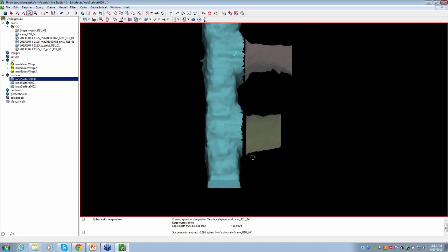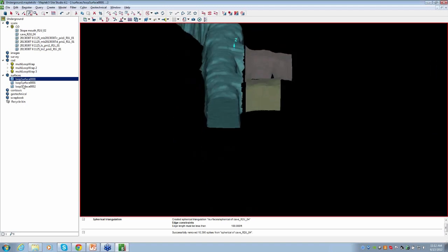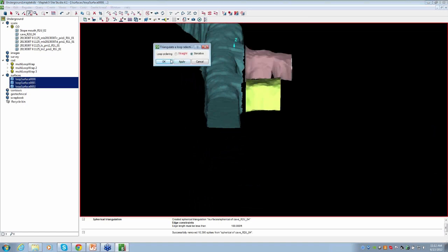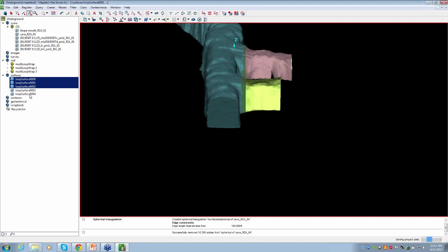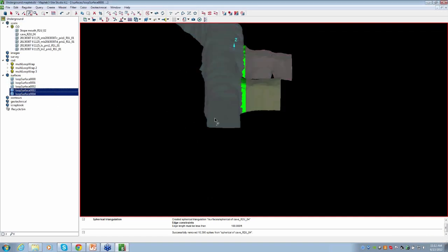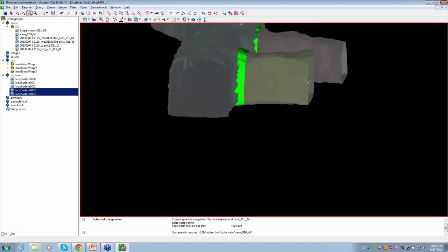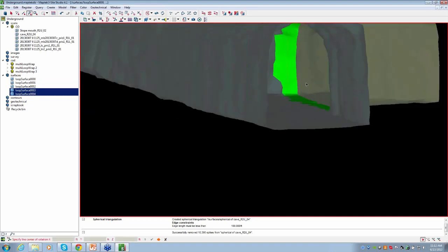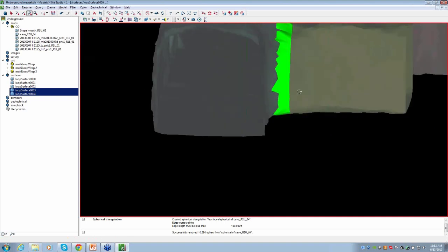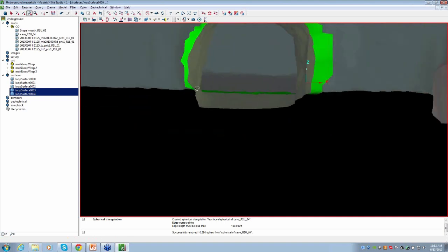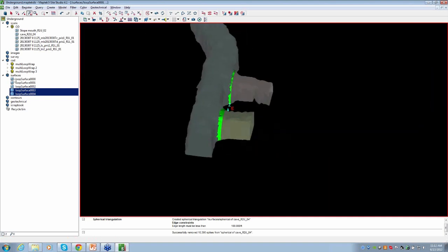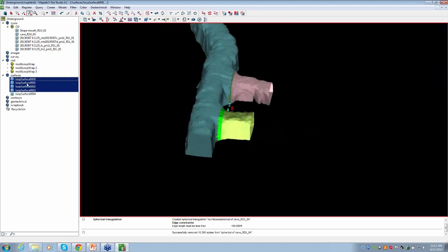All right. So now I've got that little bit of a gap there, and I'm going to need to clean that up. So I'm going to go ahead and actually loop triangulate those together, and all that does is create more. So now I've got 5 of them, but if we come in here and take a look at these, you can see that now they've actually been joined together. There's not a wall there in the middle. This is much more accurate, but we've got 5 triangulations for an area where we should only have 1.